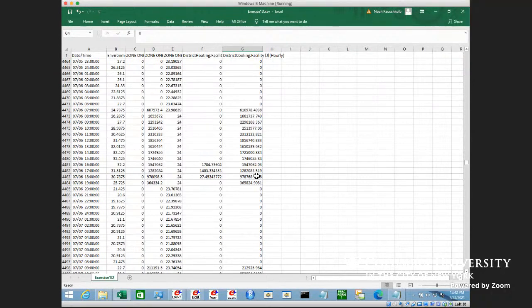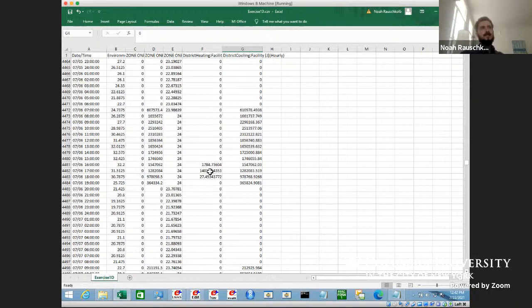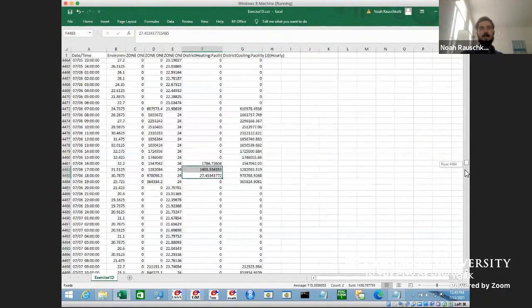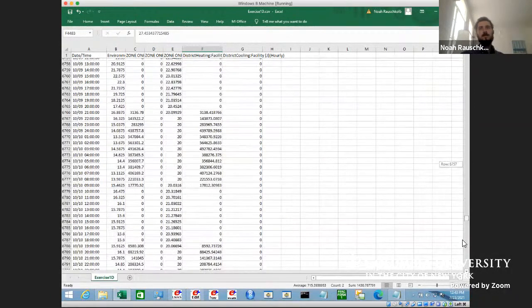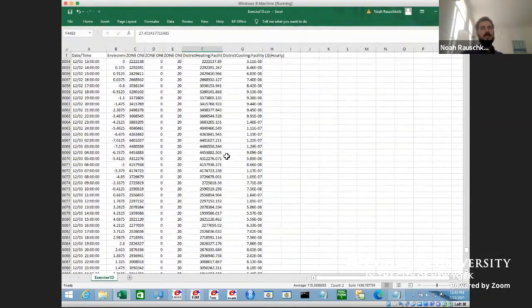Got it. So anyway, you get to the middle of the summer and you see that there's this very nominal heating demand at some points that wouldn't actually be met, but for the most part, you're doing cooling. When you have simultaneous heating and cooling, it's normally because you've got high dehumidification. So it will cool the air down a little bit more than it needs to, to suck a little bit of extra moisture out, and then it will reheat the air. And that's actually remarkably common in real world applications. So you sometimes see some heating during the cooling season, but you rarely will see any cooling during the heating season. And here, where it looks like it's cooling, this is really zero. I mean, 1 to the -8th joule is nothing.